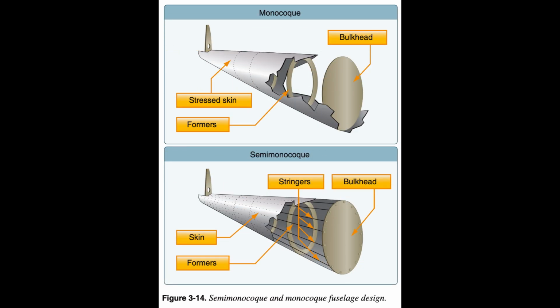The main drawback of truss structure is its lack of a streamlined shape. In this construction method, lengths of tubing, called longerons, are welded in place to form a well-braced framework. Vertical and horizontal struts are welded to the longerons and give the structure a square or rectangular shape when viewed from the end. Additional struts are needed to resist stress that can come from any direction.